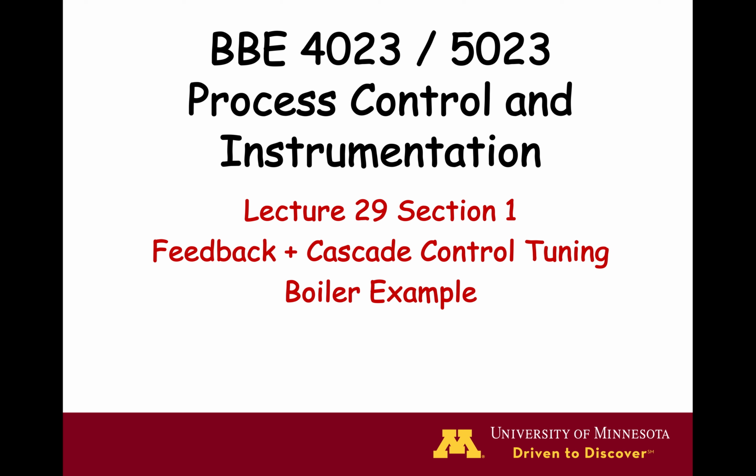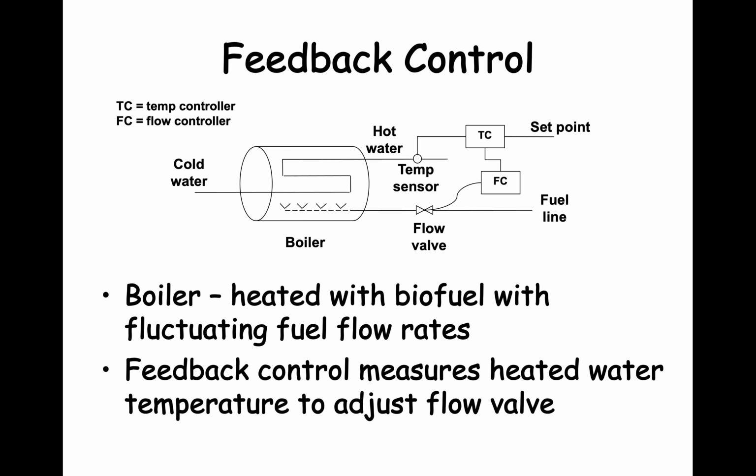The main reason for using a boiler example is to provide a physical case or framework for what we're doing. One thing to remember about boilers is that they are a slow process. It commonly takes a fairly long time for the water temperature in a large boiler to change in response to a change in the fuel input. Boilers have a lot of thermal mass.